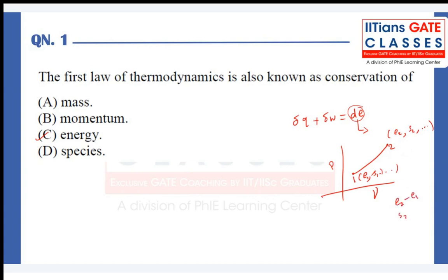It depends on the state of the system. It doesn't depend on the path through which the process has taken place. So those kinds of variables are state variables. Whereas work or heat transfer, here Q is heat transfer per unit mass and W is work per unit mass, are not point functions. These are path dependent. If I have a process A going from 1 to 2 along this path, whereas process B goes along a different path, the work transfer or heat transfer will be different.